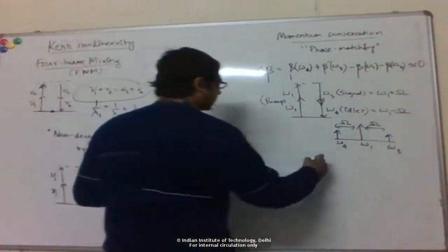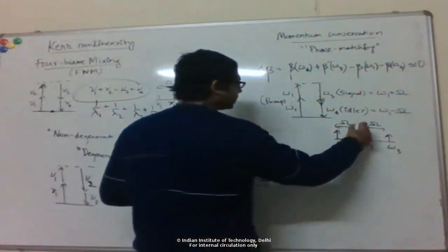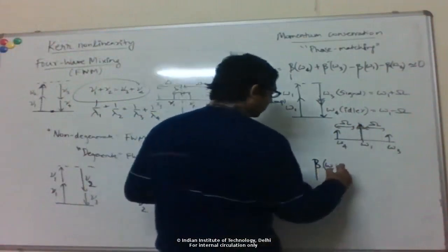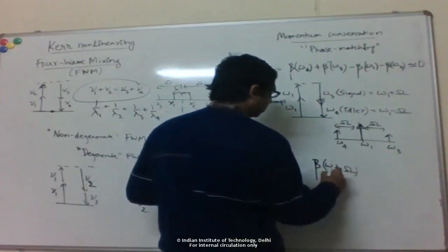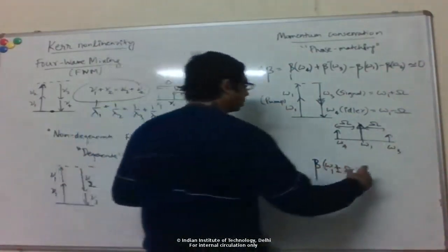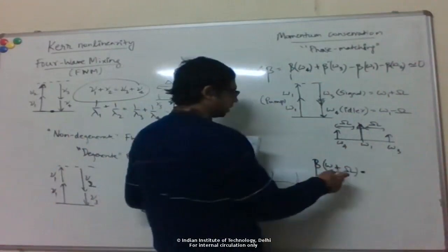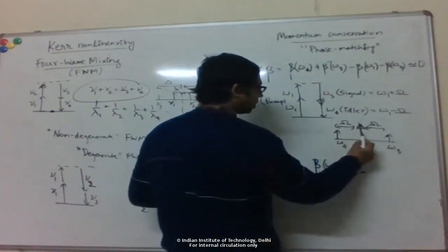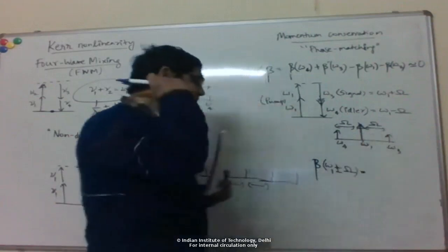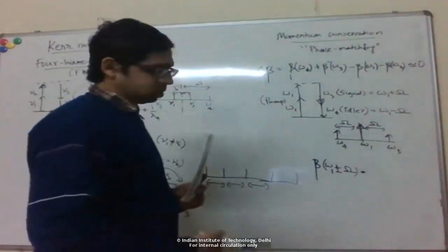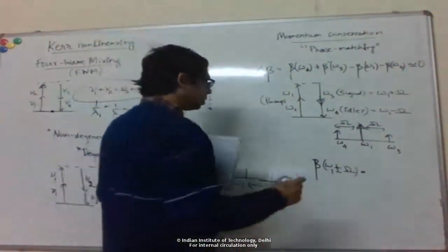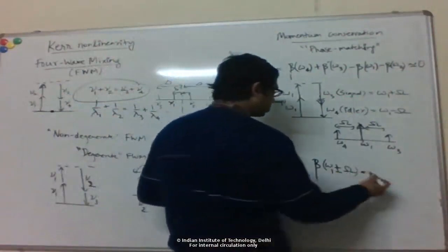Right? So for example, since omega 1 is the center frequency, and I'm looking at plus minus from that center frequency, I use Taylor expansion. Typically, of course, this is valid because now the channel spacing is much smaller than the frequency. So the channel spacing we're talking about is 100 gigahertz, hundreds of gigahertz in that range, whereas this absolute frequency is in hundreds of terahertz, right? So this is much smaller than this, so we can use a Taylor expansion